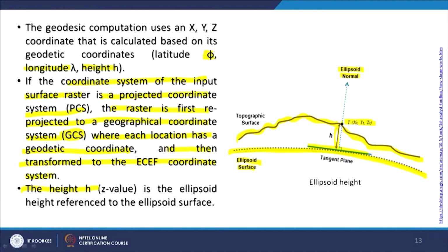And as height is z, the z value here is the ellipsoid height above this surface, whereas we say above mean sea level. So, this reference becomes our ellipsoid, though that can also be adjusted to above mean sea level. But again, that depends on the model based on our gravity surveys of the earth, that is the geoid, not the ellipsoid but the geoid, and based on that, heights are influenced or estimated.